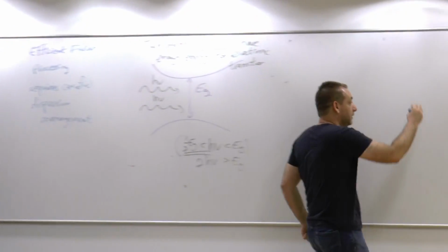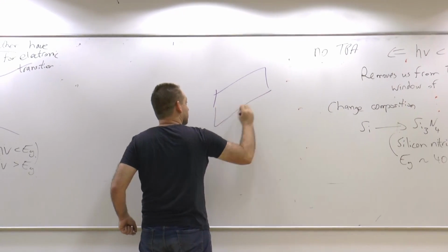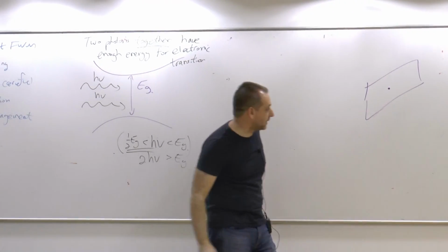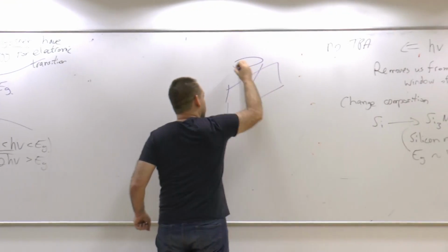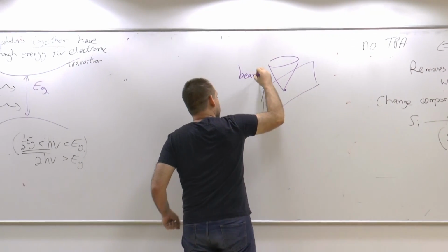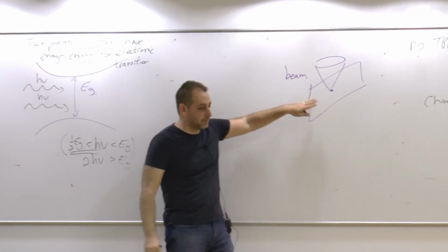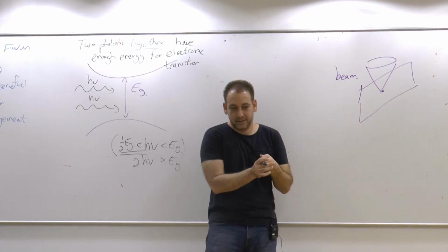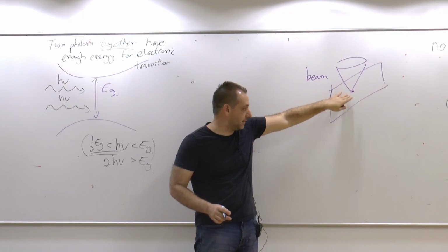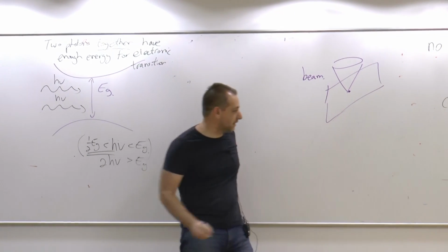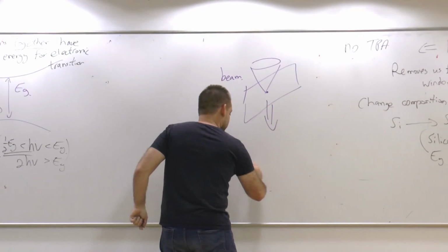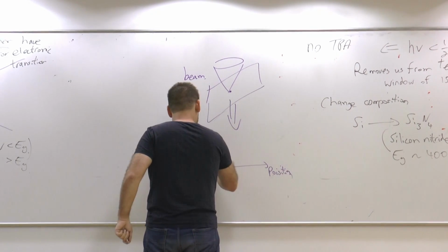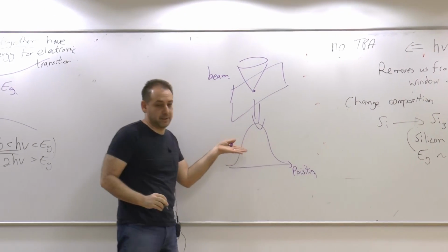So suppose that I have my wafer here, some piece of material, and I want to define a very small pattern. So what you do normally is focus a beam of light to a spot like this, and I would apply some kind of a photosensitive material called a photoresist, and it will react to the illumination and chemically modify at this region of illumination. So let's zoom in here. So as a function of position, we have some kind of intensity profile.